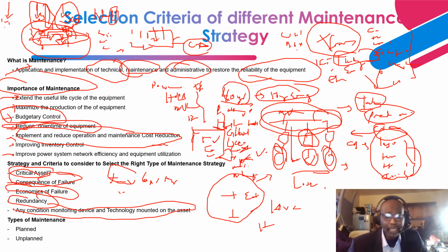The first one is bushing monitoring devices that measure the capacitance, the power factor, and also leakage current and the wattage loss. You can also install dissolved gas analysis. We have the 2 gas, the 5 gas, the 7 gas, and the 9 gas, right? And in addition, it can measure the moisture level.